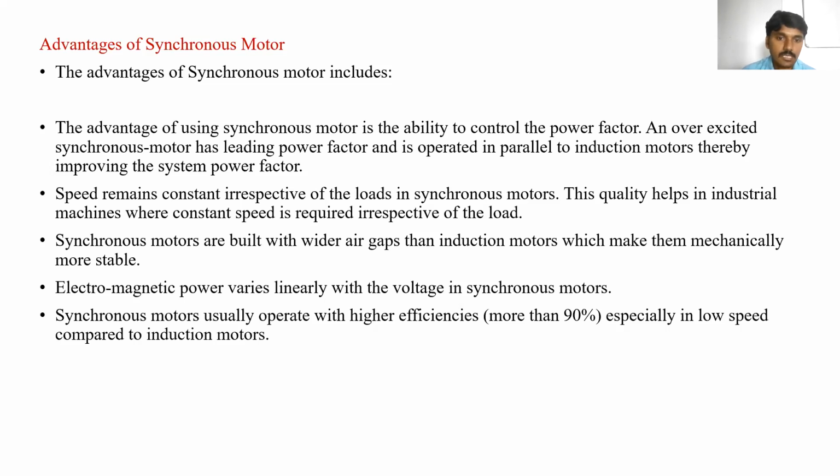Electromagnetic power varies nearly with the voltage in synchronous motors, and synchronous motors usually operate with higher efficiencies, more than 90%, especially at low speed, compared to the induction motor. So already we told that the efficiency of the synchronous motor is somewhat higher than the induction motor.